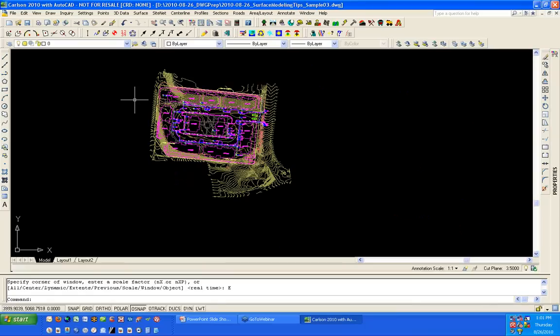And I'm going to do, now I've got points set in here. I don't actually have a coordinate file associated with this one, but I'll show you how to fix that as well. So you really want to do this first before you start elevating, before you build surfaces. This is one of the first steps.